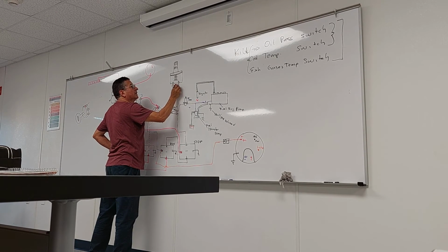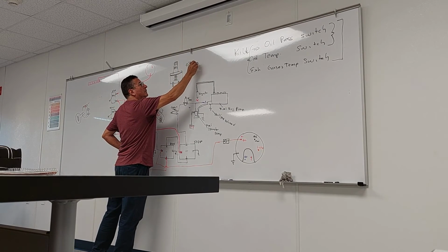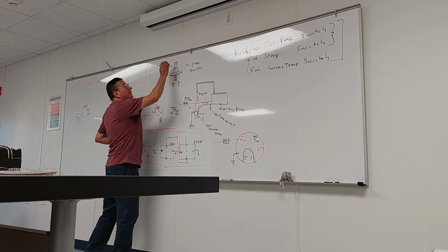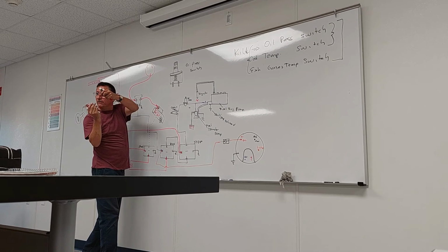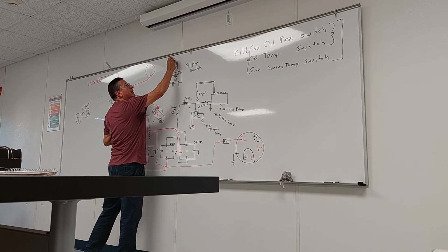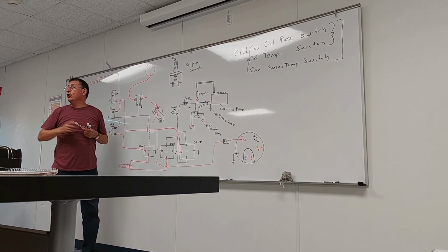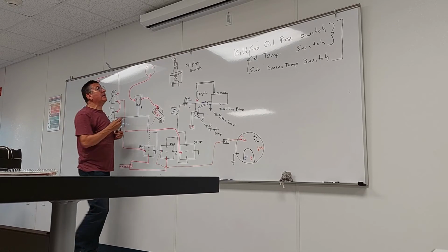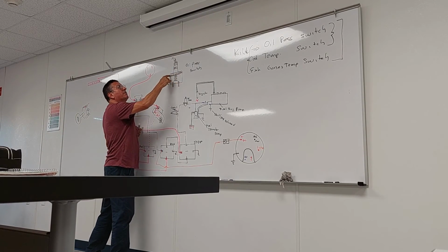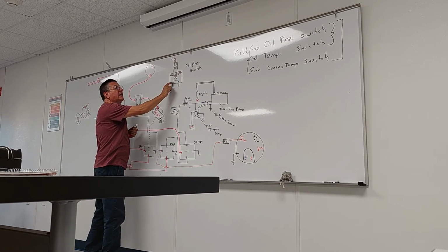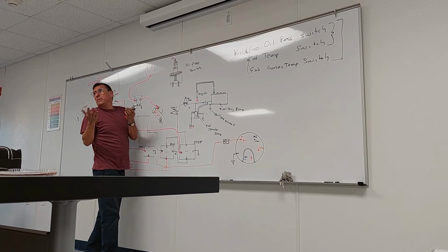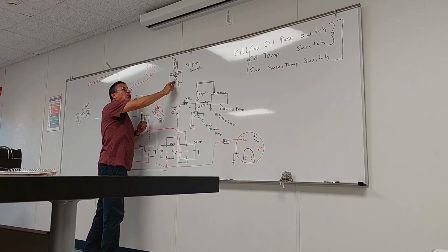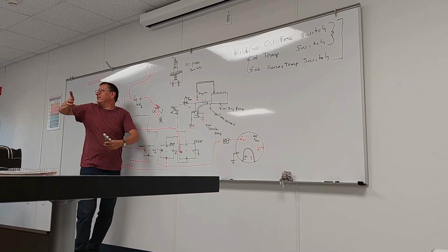Look, my friend. This is the oil pressure switch. Follow me. This one is bolted on the block where the oil filter is located. When the engine is running, the oil passes over there at high pressure. If the pressure passes the limit, what happens with the oil here, with the membrane? They are normally open or normally closed. This one is normally open. When the pressure passes the limit, what happens? It closes here, or vice versa.